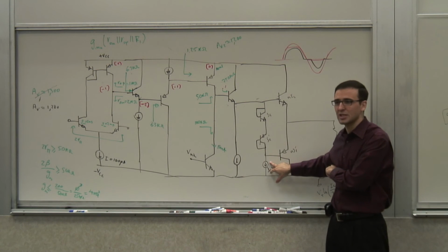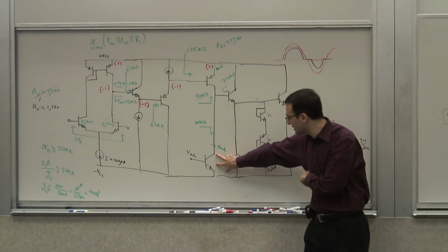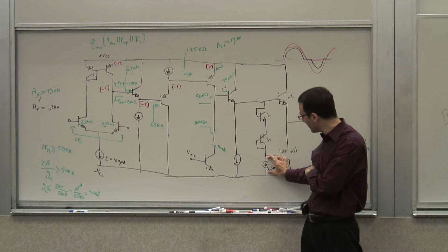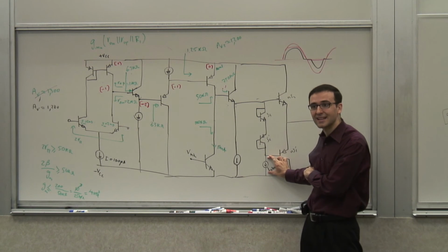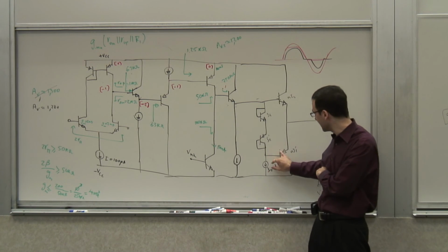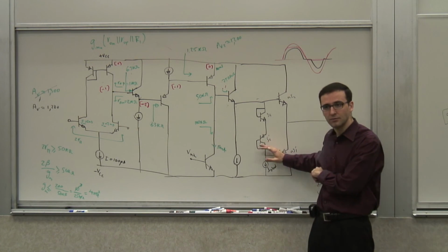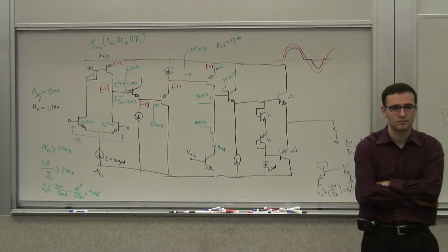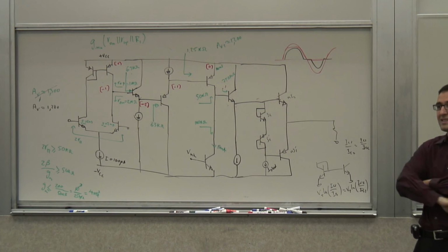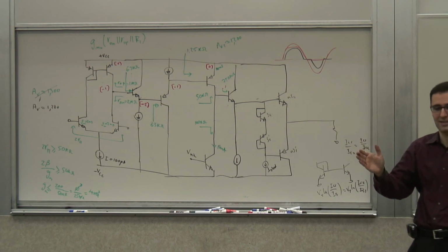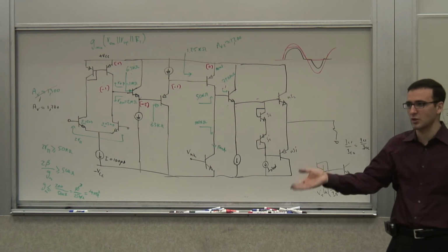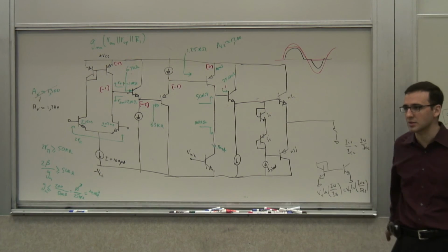Right, this guy's a transistor, right? This is the collector, so it's like this. The minimum this voltage can be is VCSAT, right? 0.2 volts. And there's another 0.7. So this will be a VCSAT plus a VBE above minus VCC. But at least, while it's not exactly symmetrical, I have a much better situation in terms of being able to go negative and positive.